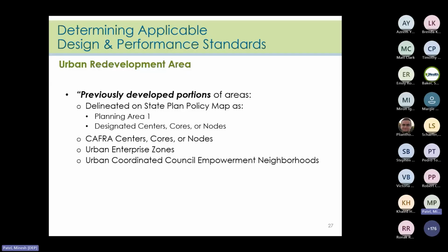If the reviewer finds that woody vegetation has returned to areas of a previously developed site, the exemption is not going to be allowed. The reason being is that removing woody vegetation and putting new construction over this portion of the site will result in a loss of groundwater recharge. And then the reviewer can check the NJGeoWeb to determine whether the rest of this information on this slide is applicable to the site.